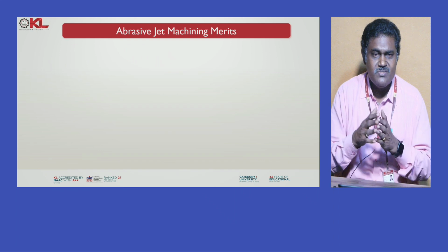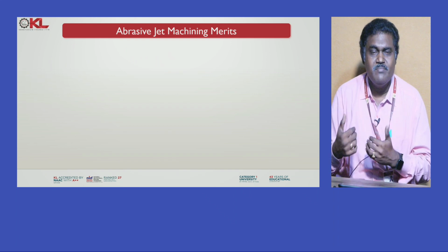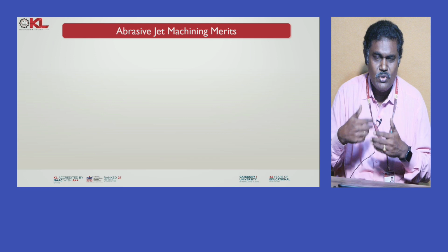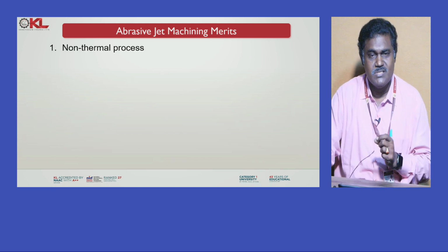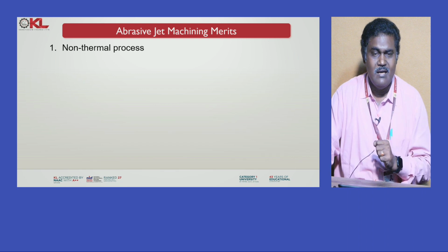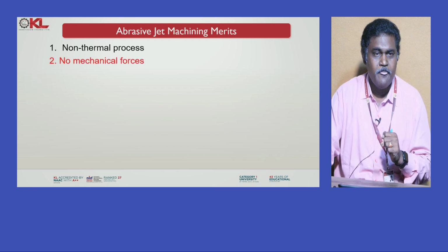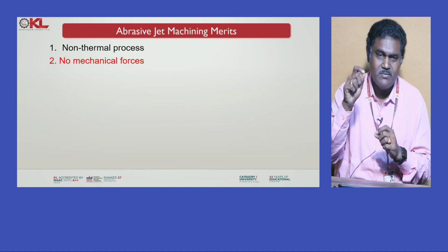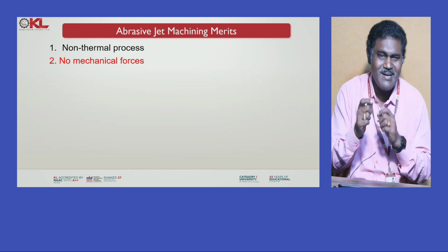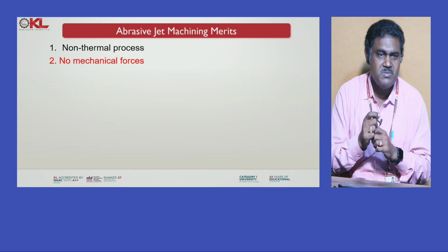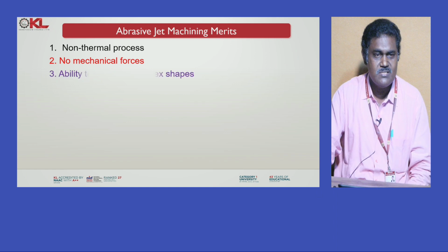Next, for abrasive jet machining, you can also learn the merits and demerits. So what are the merits? First, this is a non-thermal process. There is no thermal action on the workpiece and no mechanical forces. Here the abrasive jet is impinging on the workpiece. There is no direct contact between the nozzle and workpiece, so no mechanical forces are acting.